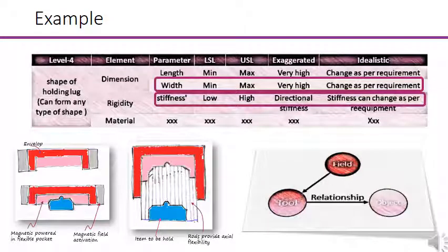The other solution is on rigidity, where directional stiffness is obtained by having a needle-like system in parallel and allowing their sliding in the axial direction. This obtains higher rigidity in the plane direction, however flexibility in the axial direction.